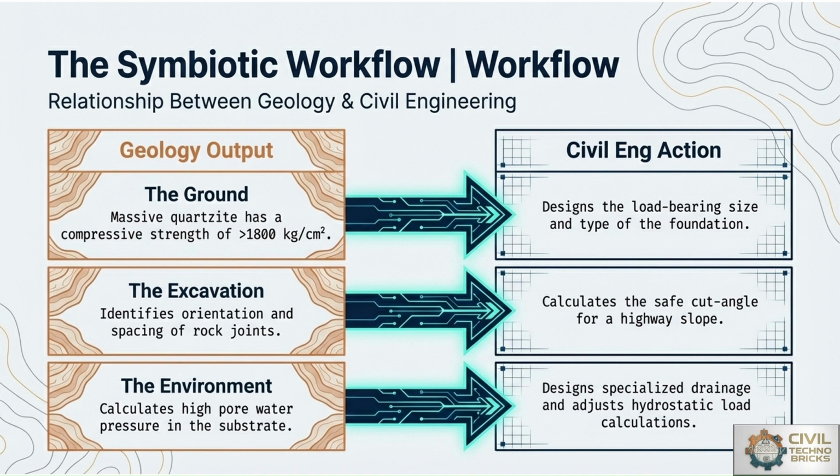Second one, the excavation, which identifies orientation and spacing of rock joints. For the civil engineering domain, it calculates the safe cut angle for highway slope design. Third one, the environment, that will be useful for calculating the high pore water pressure in the substrate or in the atmosphere, with reference to the civil engineering application, that is, designing specialized drainage and adjusting hydrostatic load calculations.